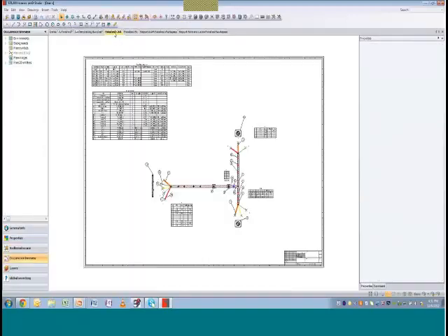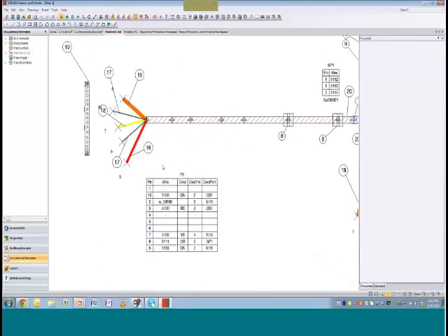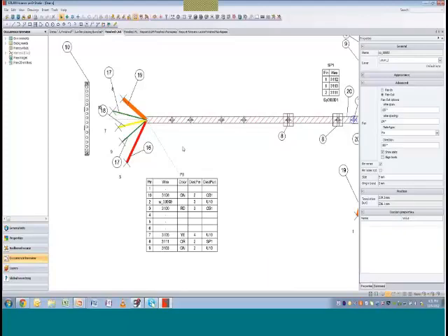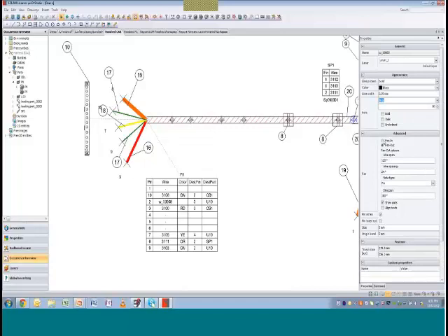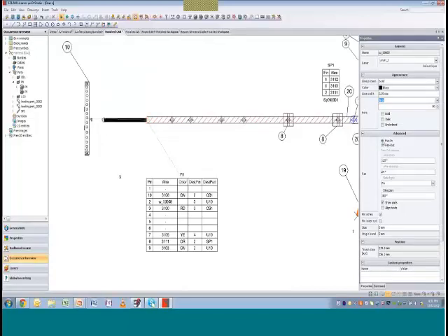In the nail board, I can see that I have my P9 connector. I can see what the connector looks like in a 2D environment and the individual connections. Once I click on that connector, I can decide whether I want these connections fanned in or fanned out. In my appearance settings, I can select whether to fan it in or fan it out, depending on how many connectors you may have and so on. You can also define the spacing and the direction and how those are going to be arranged. So it's very easy to customize and move things around if you need to.